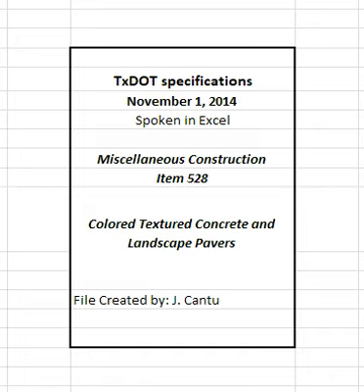5.2 Landscape pavers. The work performed and measured as provided under measurement will be paid for at the unit price bid for landscape pavers. This price is full compensation for furnishing, placing, and compacting pavers, bedding and joint filling sand, and equipment, labor, materials, tools, and incidentals. Paver units damaged during compaction will be replaced at the contractor's expense. Base required for landscape pavers will not be paid for directly but will be subsidiary to this item.